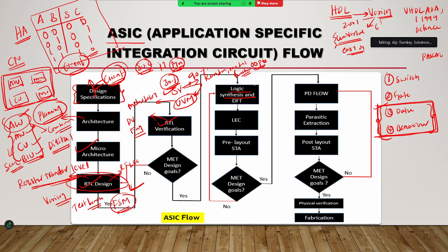Logic synthesis is nothing but what? Some constraints will be there. When you want to make an IC, you need to take care of area constraints, power constraints and timing related constraints. What is the difference from high level languages like C, C++, Java?